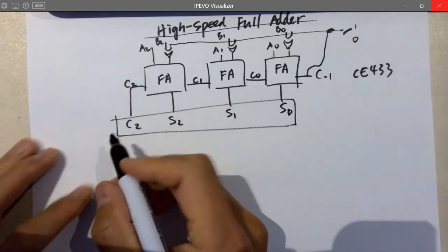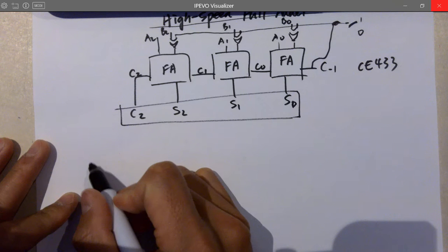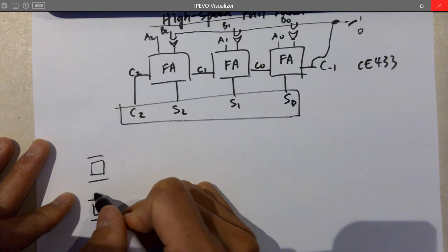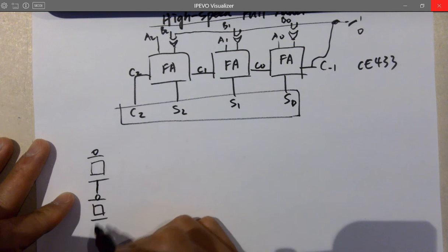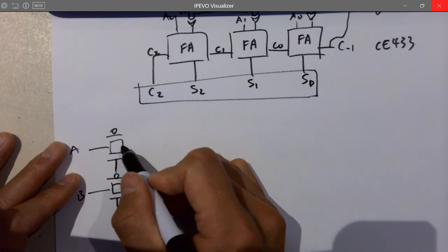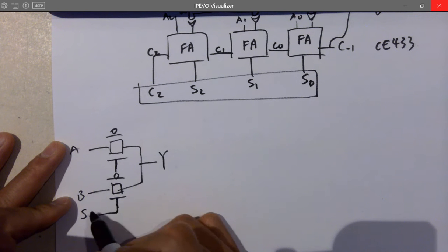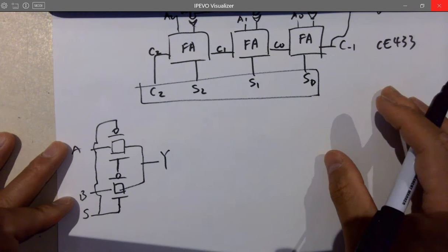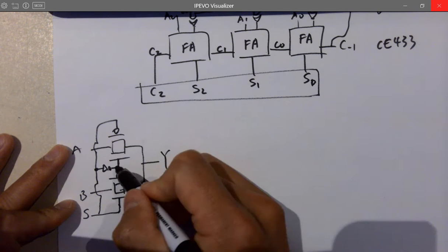And another one, we brought this up on Monday. A, B, and that's Y, the output, and you need an S, a switch, connected to the NMOS here and the PMOS here, and it needs to be inverted and connected to the other pin.